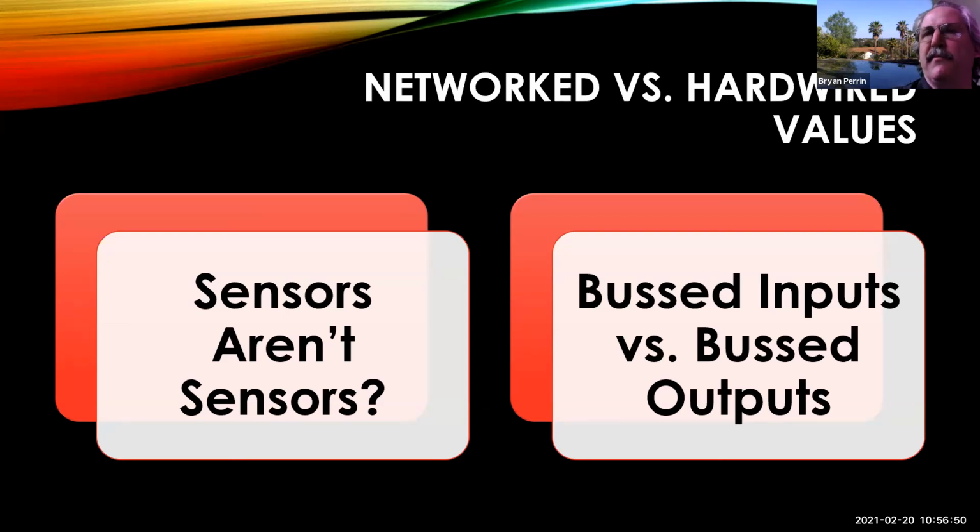And my sensors, my inputs, may also be coming from other places, not directly from that module. For example, the outside air temperature sensor may come straight to my HVAC module, but it's shared with other systems. Or it may come straight to my instrument cluster and then be shared with HVAC. Both modules may have a temperature PID.